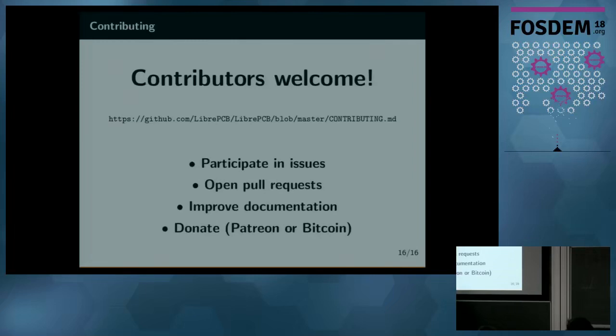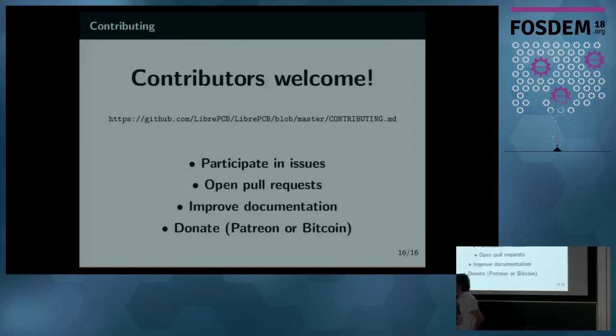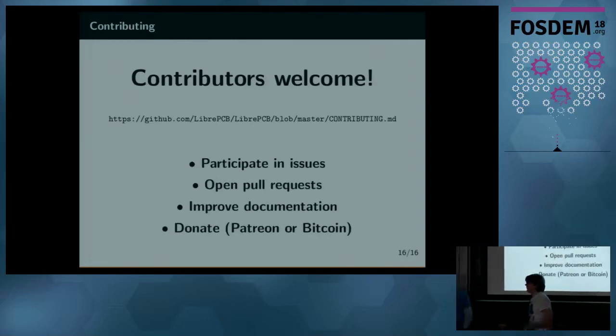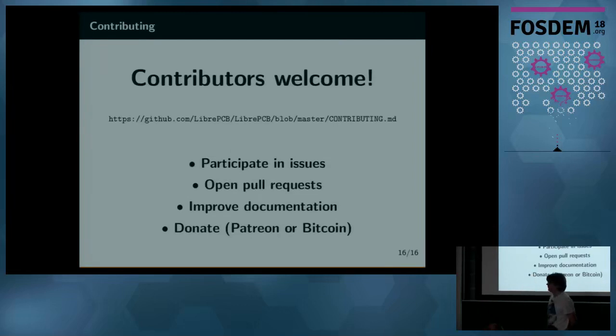So, where do you source all the different bits? You can say I want a BC547, but then there are many different ones. So your question is about generic devices, where to order them then? Like order codes from different vendors. Yeah, this is something he didn't solve, right? So you can source it from DigiKey or Mouser or other suppliers and add this in the libraries.